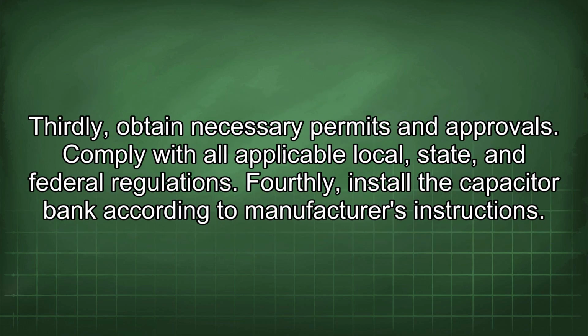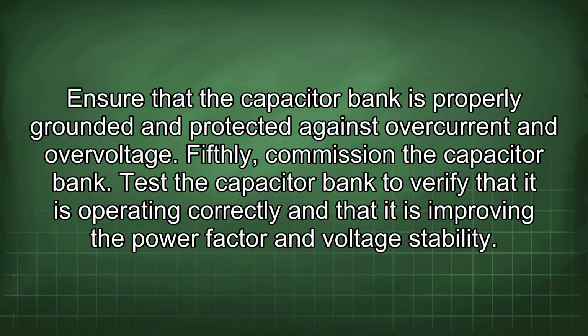Thirdly, obtain necessary permits and approvals. Comply with all applicable local, state, and federal regulations. Fourthly, install the capacitor bank according to manufacturer's instructions. Ensure that the capacitor bank is properly grounded and protected against overcurrent and overvoltage.